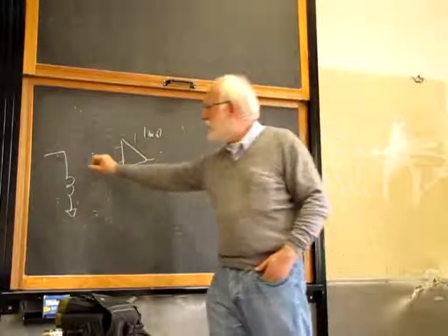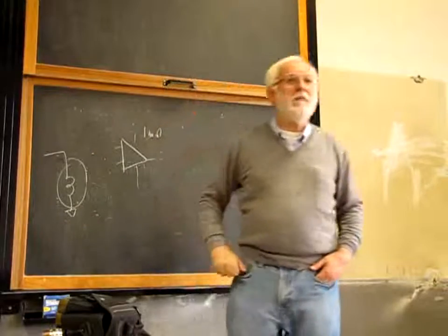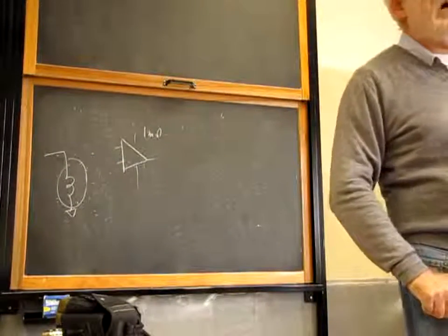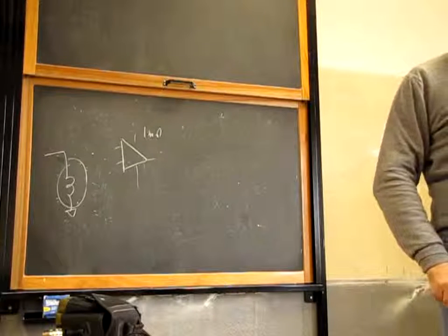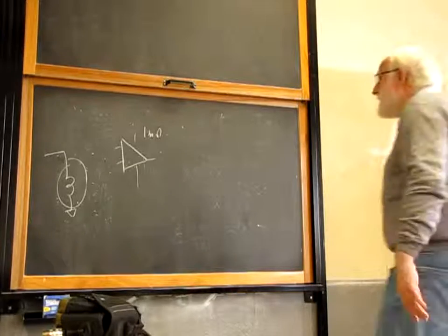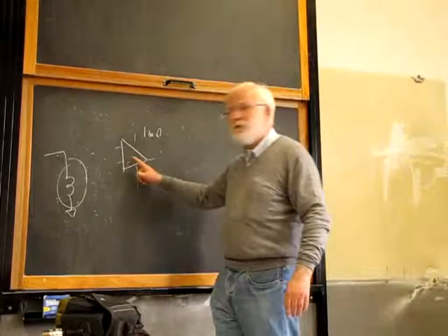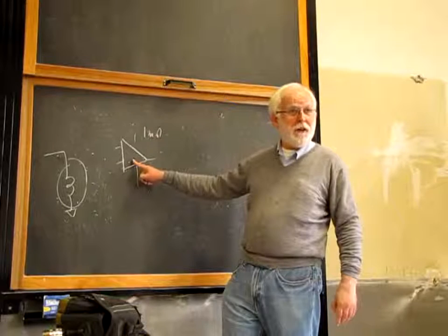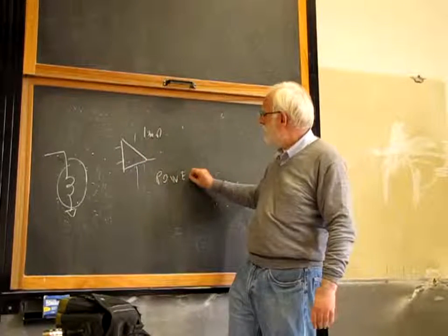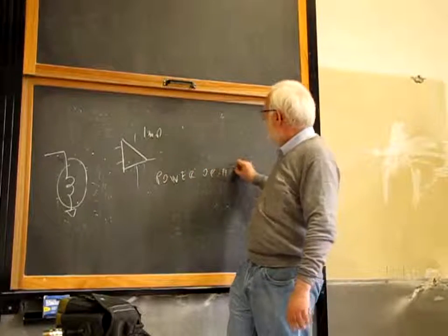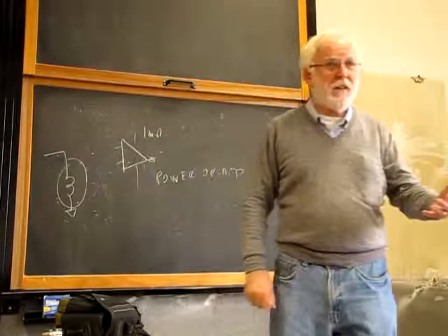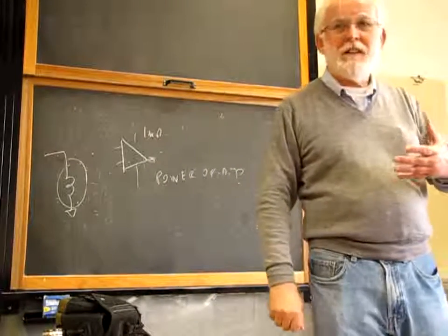The fact is that in switch mode power converters, inductors carry a current of the order of amps, a large current. If you want to synthesize an inductor using a gyrator with an op-amp, you need a power op-amp, one able to deliver amps of current from its output. Exactly the same current goes through the inductor.